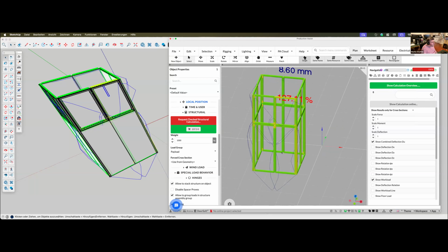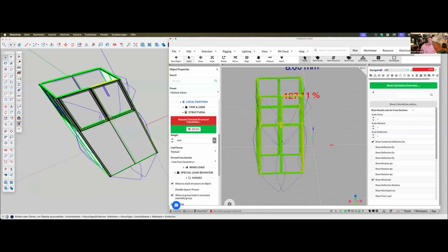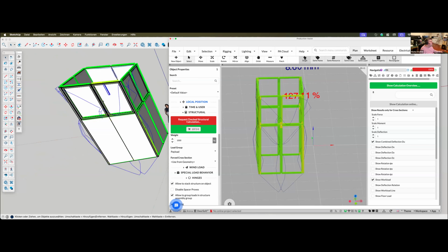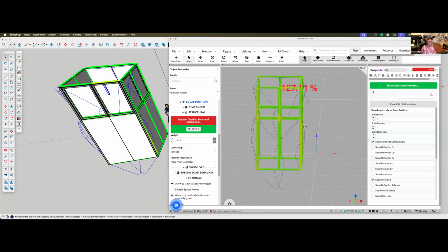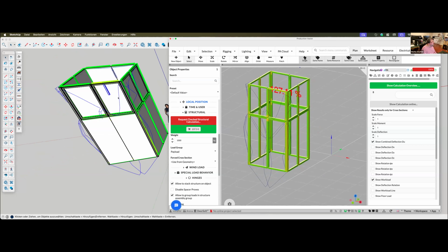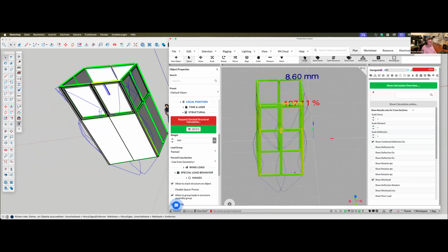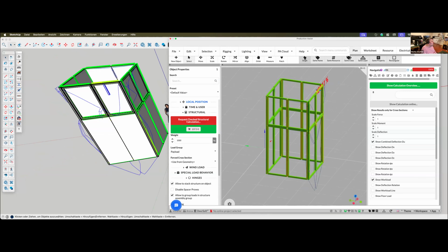You see right now, and you also see it a little bit in the deflected shape in here, that basically when you use the click on connect button, it will add 2 connectors per each side of the frame in here for the calculations. So if you now would duplicate these connectors in here, you actually would be able to withstand this 1,000 kilo load in here, so that it doesn't tip over.